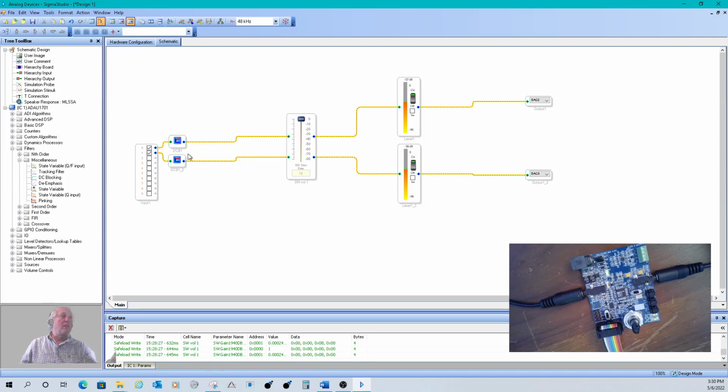Now see, once I started adding things in, we went back to design mode on the bottom right, and nothing's happening here. I wouldn't be able to change anything. But the program's still running in the DSP. I can still play music, but we have no control over it. And it's the old program. So let me reload this new one. So link, compile, download. And boom, look at the meters.